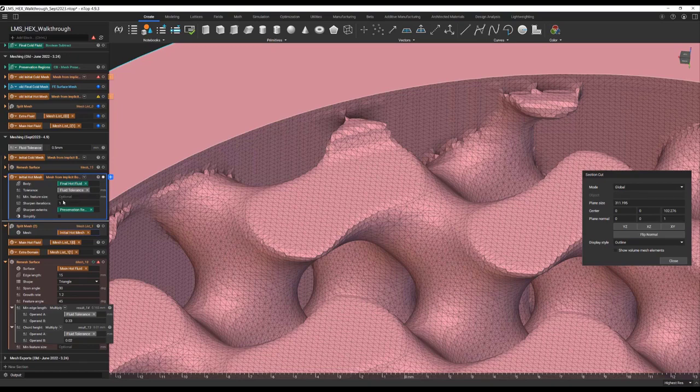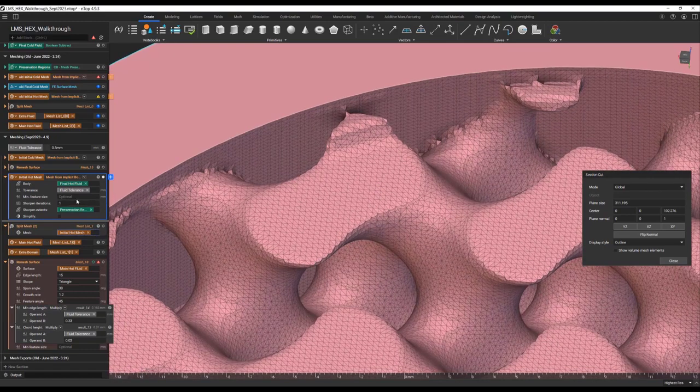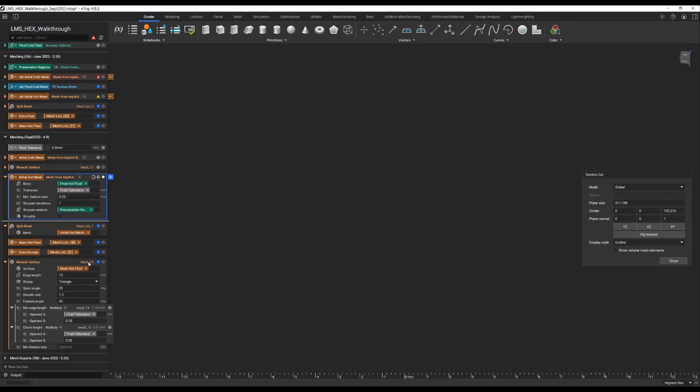And all this is going to do is tell the mesh block to ignore any implicit parts that are below this value. So I'll just put in 0.25, see what happens. I'm going to click manual run mode on the split mesh so we don't start the other processes.